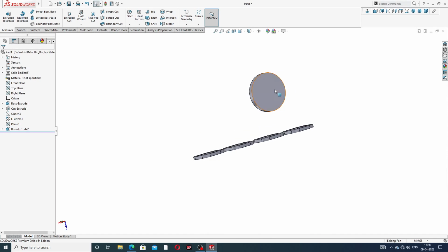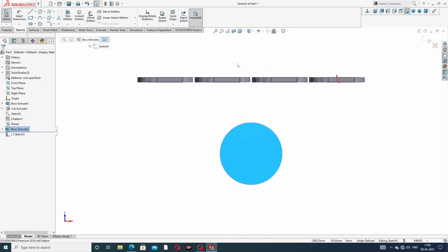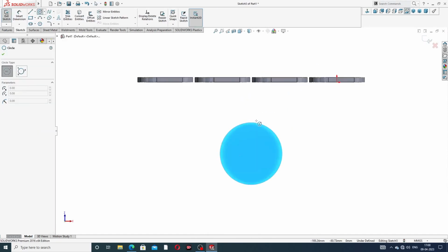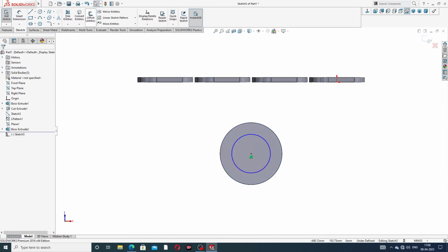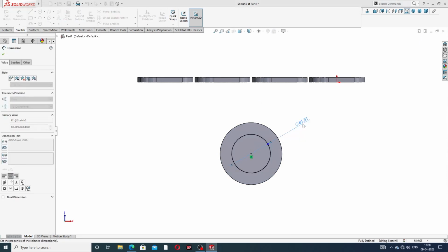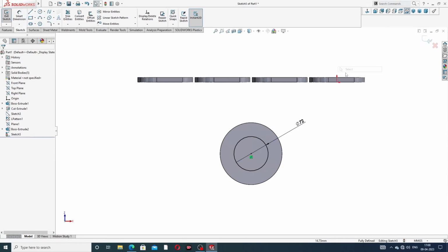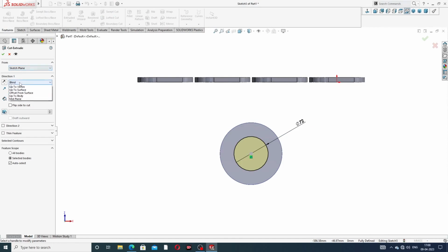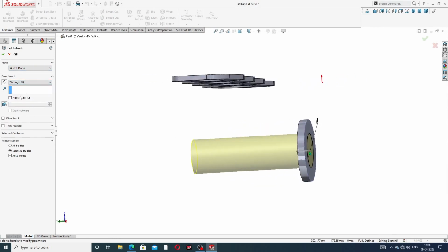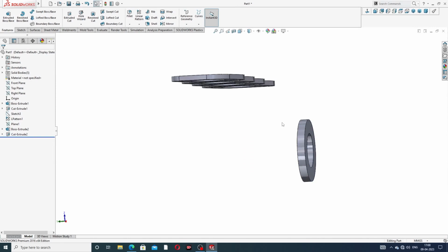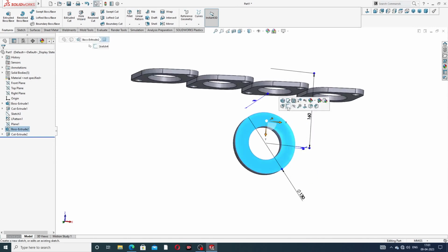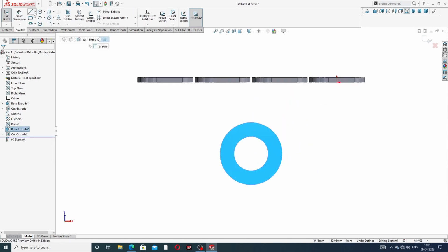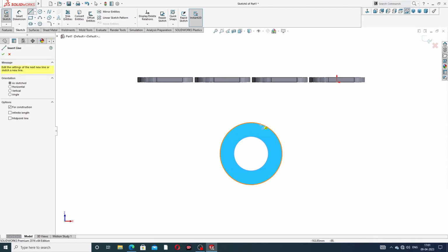Okay, and also this sketch normal and drawing a circle here, and this circle is cut out, and use 72 millimeter cut out is perfect, and use an extrude cut, use through all, and click OK.